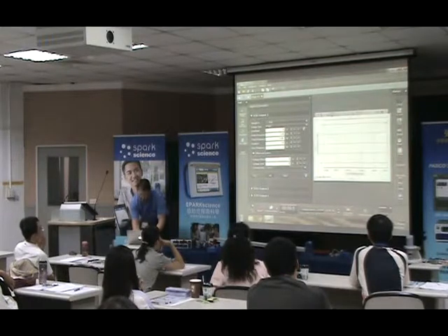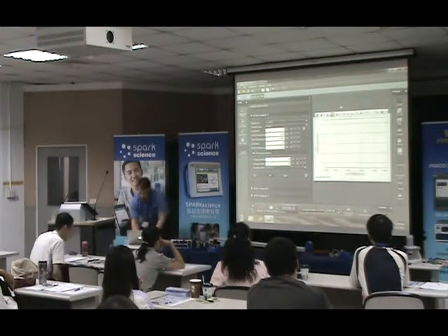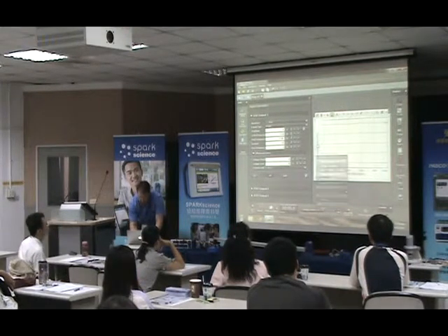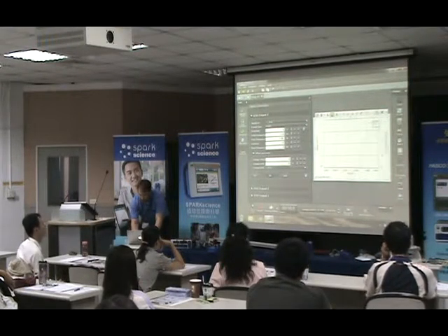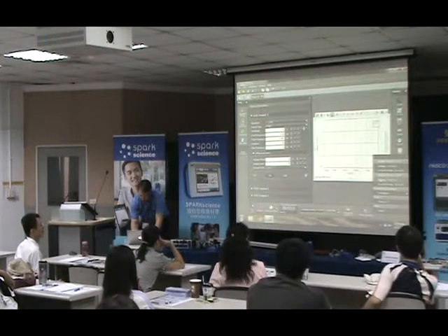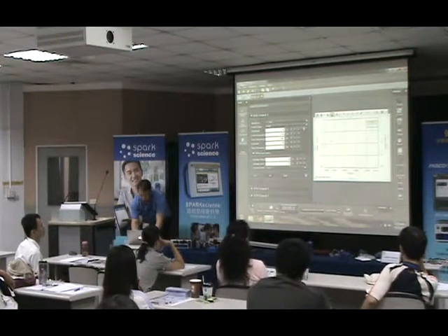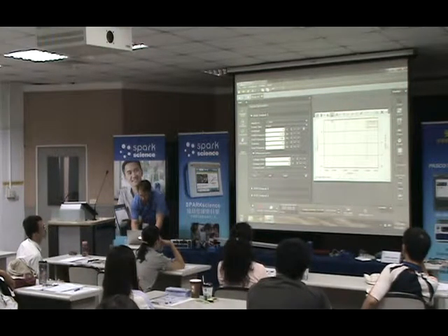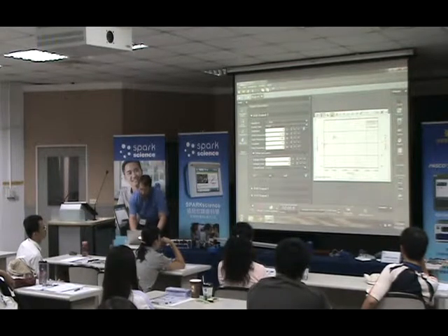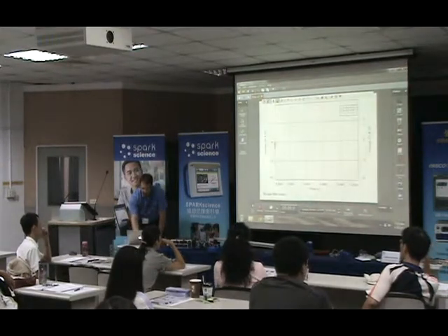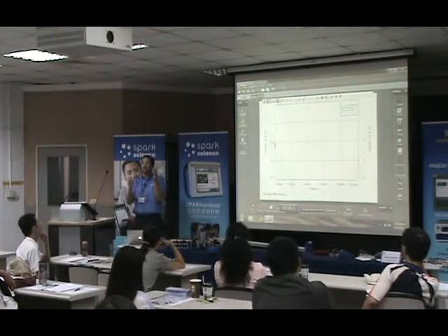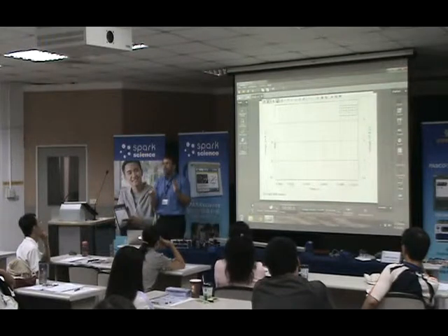and open up a scope. And I apologize, my screen is a little small, but I think you'll be able to see. So I'm going to add my 2 voltage sensors to my oscilloscope. So that's voltage A, this is voltage B. Okay. I'm going to go ahead and turn on a trigger, okay, because I want to see a nice smooth circuit here. And the last thing I want to do to my oscilloscope display is I want to adjust it to a time window that I can really see this circuit form, right?